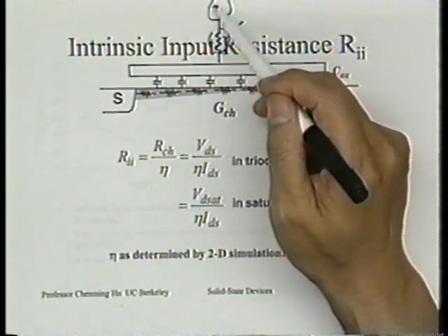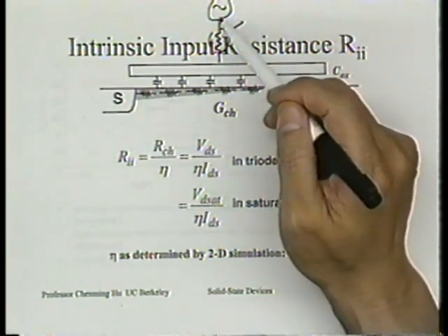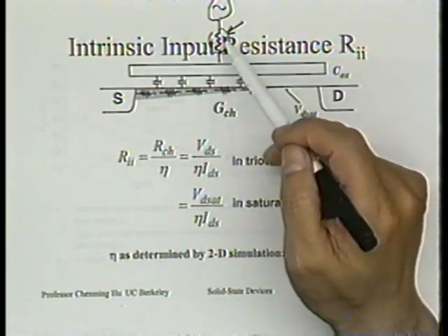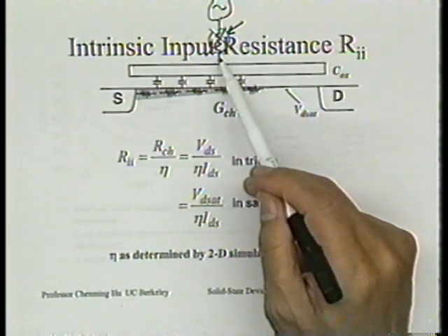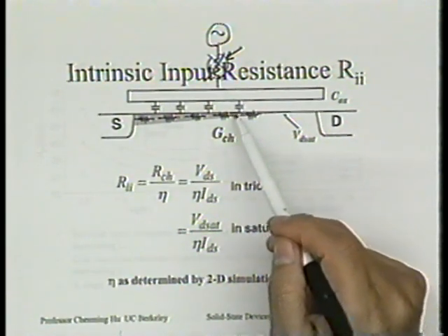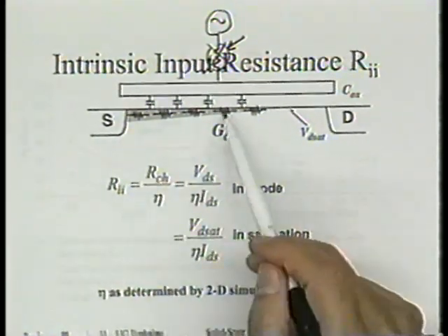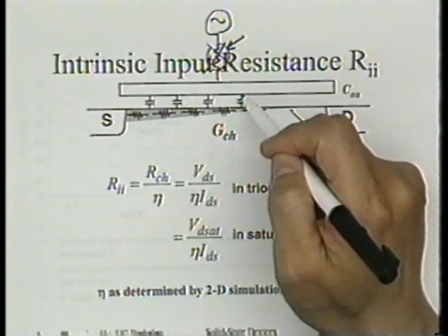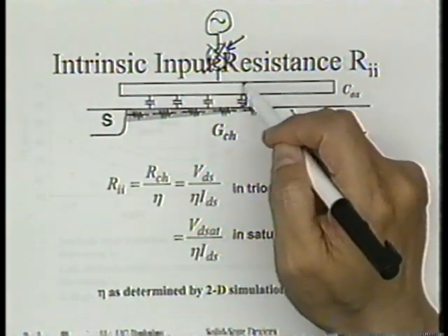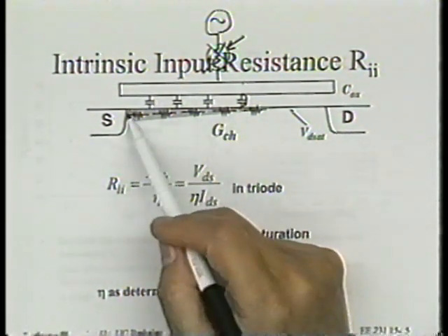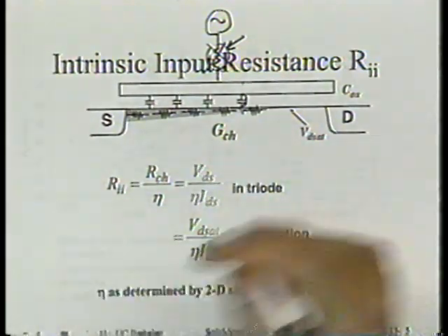It will flow from the voltage source of the gate voltage across this polysilicon resistance, or even if there isn't any there, this current will flow across the resistor, a capacitor, and then reach the ground. But between this point and the ground, there's still resistance, isn't there? So as a result, the voltage drop across the oxide, let's say at this point, is not the full VG, but VG minus the voltage drop due to this resistor and the AC gate current.